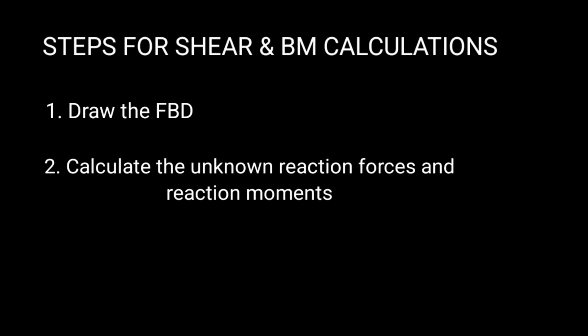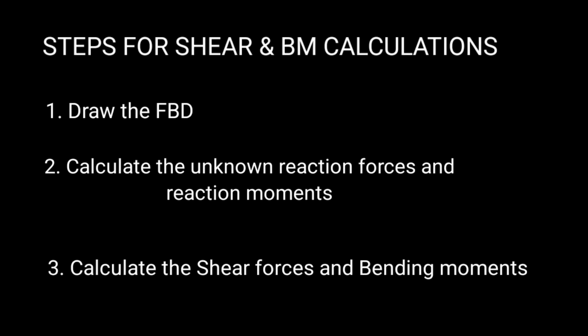Now let's see how to determine the shear force and bending moments within a beam. There are three main steps we need to follow. First one is to draw the free body diagram. Second is to calculate the unknown reaction forces and reaction moments at the supports. Next is to calculate the values of shear forces and bending moments at preferred locations along the length of the beam. I will explain these with the help of an example.